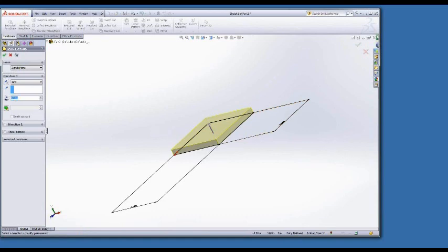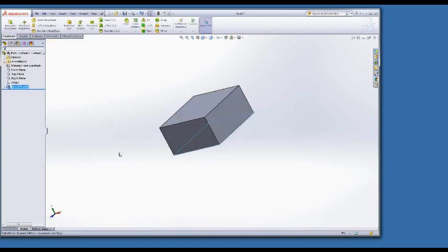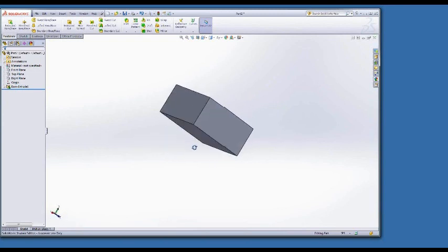Let's make this, for our sake, let's make it a 1/2 inch wide. So I'm going to type over right here where it has the depth or dimension right here. I'm going to type 0.5. I don't have to say units because right now it's considering inches to be my units, but if I wanted to, I can. Where's inches? There it is. And then I'll hit enter. Make sure that's what I want, and again I can go ahead and click the checkbox, and it now has turned that into a solid. So I have now drawn my first 3D solid.